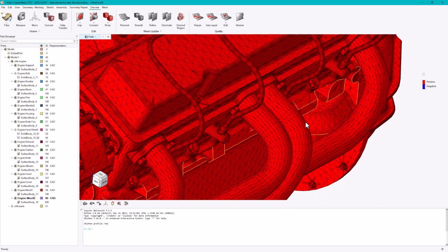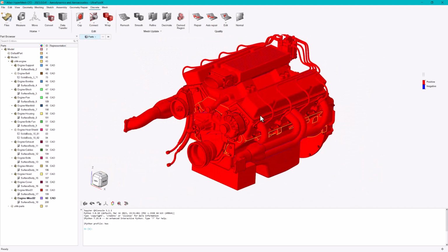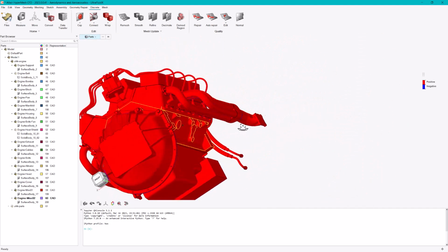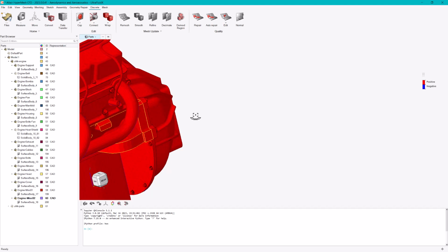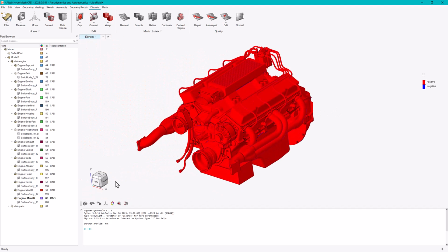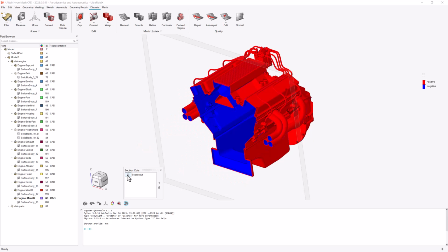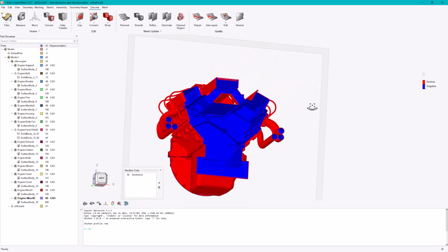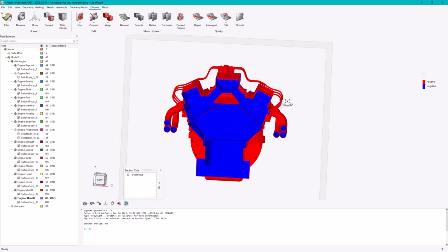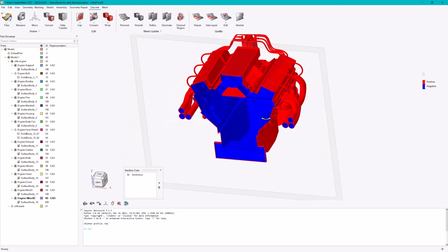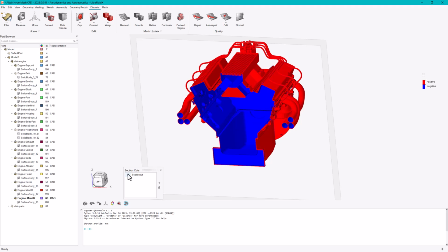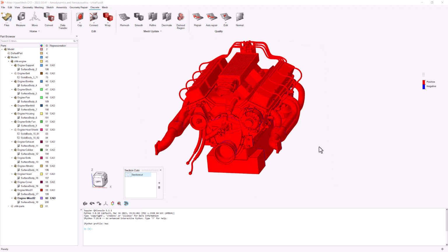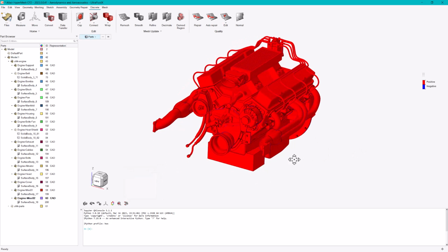If there are any issues, you can also check the details or small places around this part. And then you can also turn on the section cut. Again, the internal surface in this case will be shown as blue. Again, this is what it will show as a one closed shell wrapped mesh. And then, so that's the wrapping process.